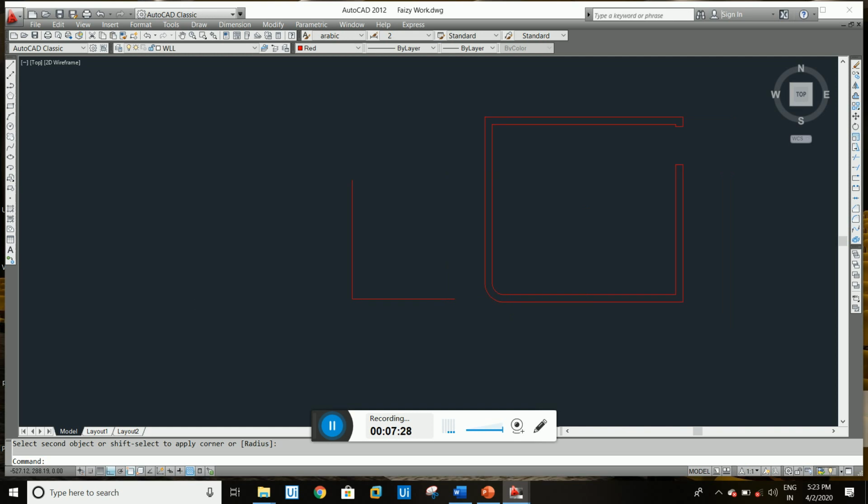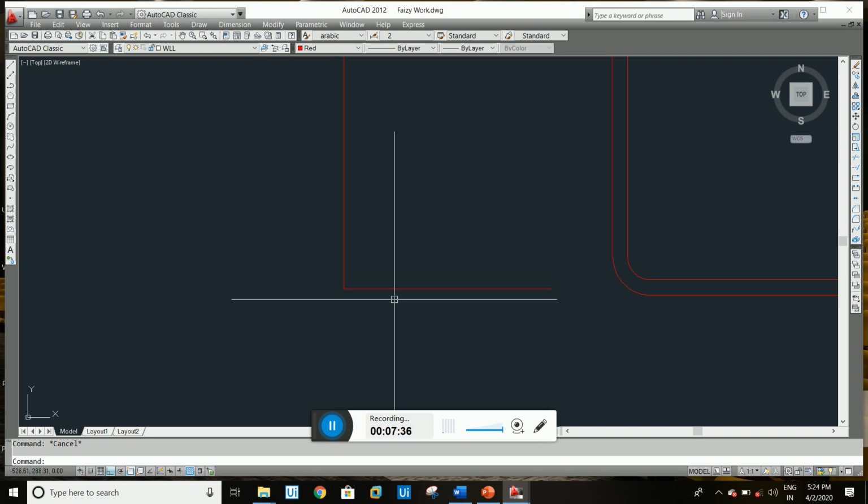And the next thing we need to cover, guys, is the chamfer command. The chamfer command creates an angular line here to make a chamfer. For chamfer we use the keyboard. The command is CHA, chamfer, enter. In chamfer we see some help menus come up here, and we have to choose distance. For distance, how much distance you want from here and from here to make the chamfer.